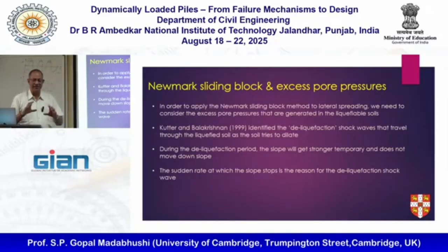Soil liquefies around the tunnel and it floats up. You can do FE stuff and so on. I think I showed you an example of that before. But you can actually predict the upward movement simply by using Newmark's same concept of threshold acceleration. And it works beautifully. Because the mechanics is easy, it should work.